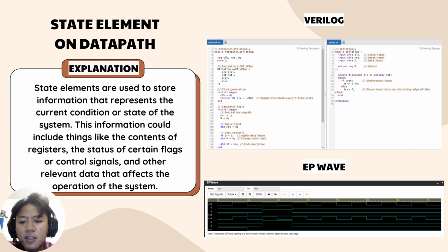Next one is create state element on datapath. So what is creating a state element on datapath? State elements are used to store information that represents the current condition or state of the system. This information could include things like the contents of register, the status of certain flags or control signals, and other relevant data that affects the operation of the system. So basically, the coding for creating state element is in Verilog, the design and also the test bench, which creates a wave, which is the EP wave, as you can see on the slide.